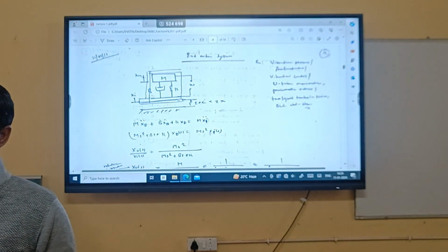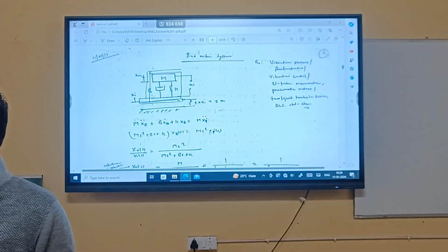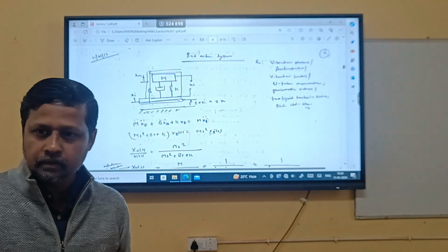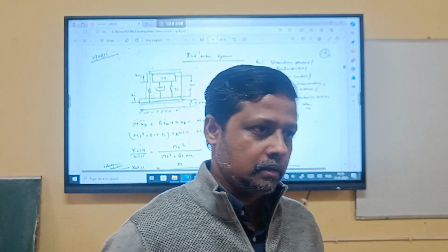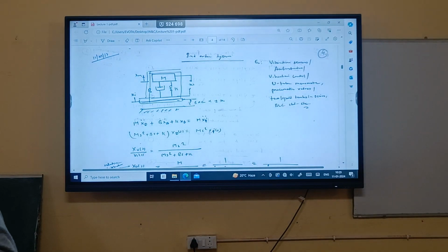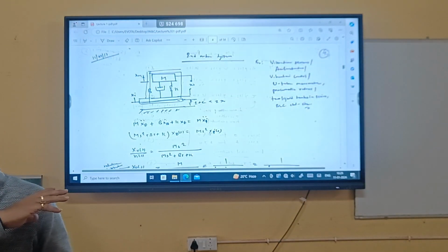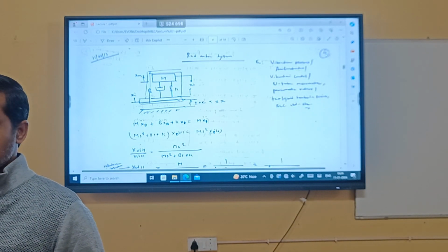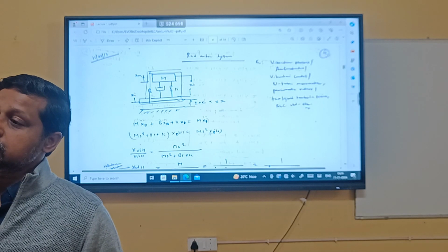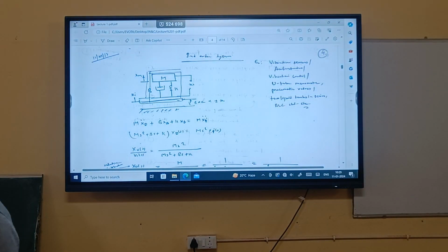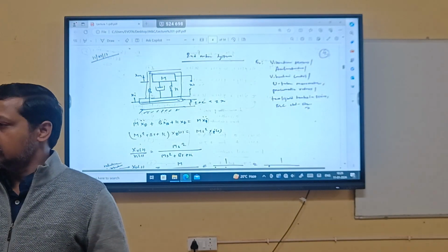The characteristic of the system will react upon it. If there are 2 real roots, the characteristic will be different. If it is a complex conjugate pair of roots, then the characteristic will be different. Is it clear? Based on that, because it is a second order system, if damping is one of the factors, then based on damping we can further classify in 3 acceptable categories, I would say: overdamped, critically damped, underdamped.